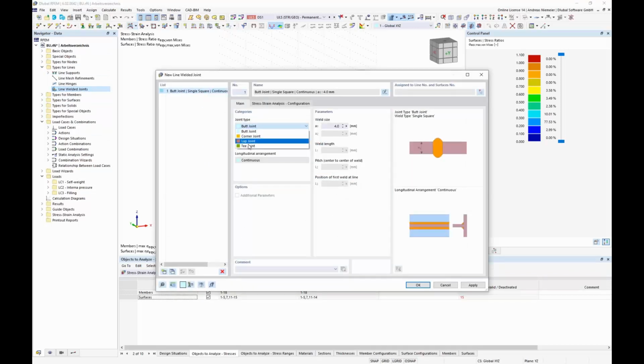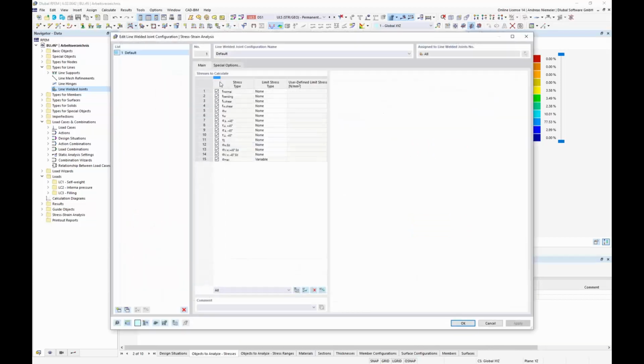For example, a butt joint with a thickness of 26 millimeters of the cylinder. And we specify also the same here, which stresses we want to check. We say, okay, let's give us the principal force directions, but output finally the interacted stress, maybe sigma weld, and compare it again so that we have a comparison to 280.